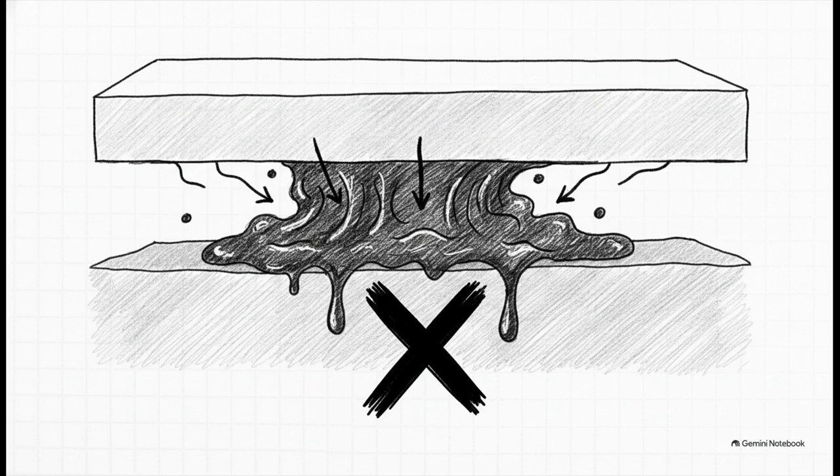Why? Well, if you pair the specific clear acrylic latex with the vinyl backing, you trigger a nasty chemical reaction called plasticizer migration. The plasticizers in the vinyl literally leach out into the adhesive, and they turn it into this gooey, permanent liquid mess that completely destroys the bond. It's a wildly expensive disaster, but the good news is it's 100% preventable if you just follow the science.